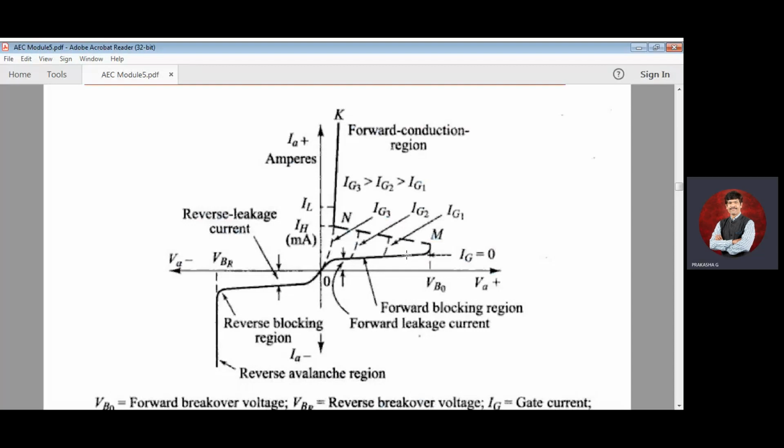So you need to define what the gate current value should be so that your thyristor is going to work. It will be giving the current and voltage itself. For a small voltage, it is going to increase. There is an experiment in your lab, thyristor characteristics, SCR characteristics. If you do this, you will come to know how exactly it is working. Even though I keep on increasing the voltage, current was not increasing. But as soon as I give a small gate current, and keep increasing, all of a sudden it comes back and then current will increase.